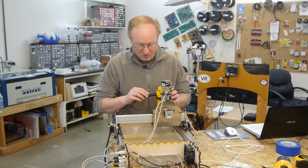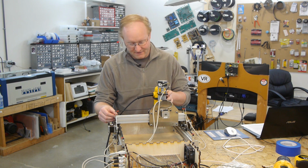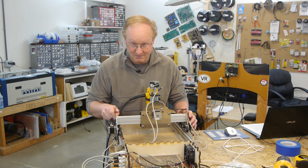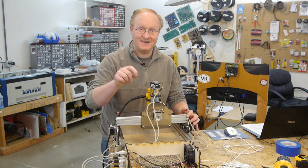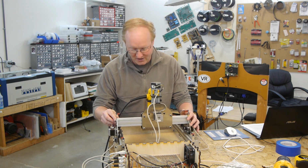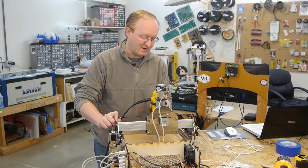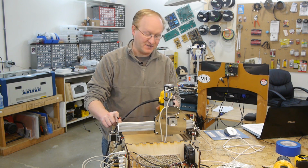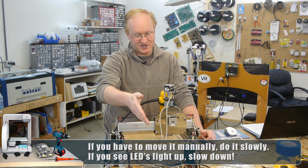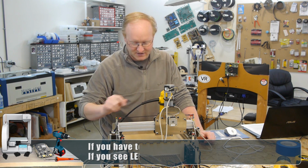One thing of note is you don't want to move the head manually very fast if the machine isn't on, because you're actually generating current in the motors, and that current will be fed back into the system, which it's not really supposed to be. So always, if you have to move it manually, always move it slowly. And if you're transporting it in a car, make sure that you have everything inert. Otherwise, like if you take a turn and this goes, right? You could send too much current back and destroy one of your integrated circuits. Those are the kind of things you need to think about when you're using CNC machines.